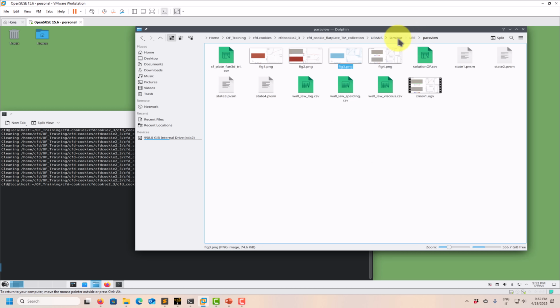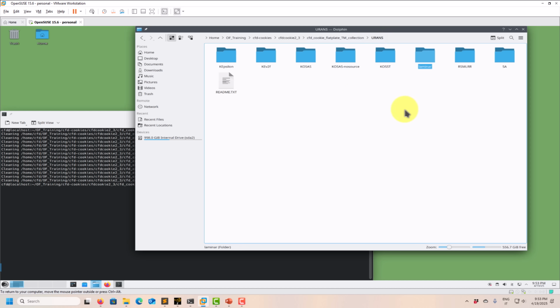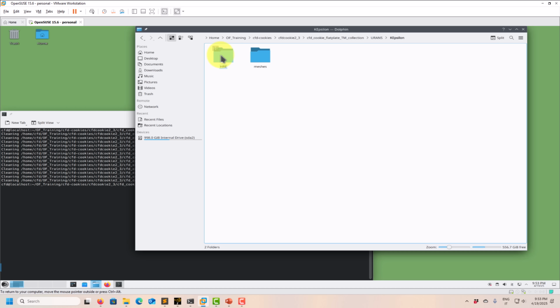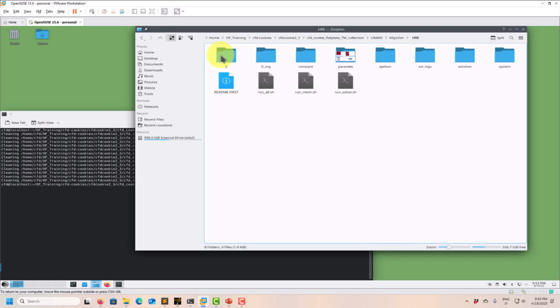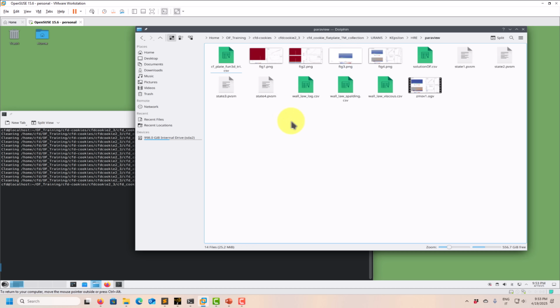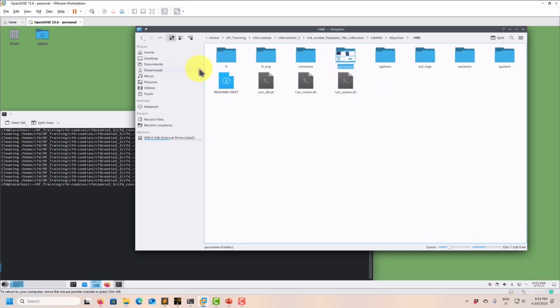Statistics are very important. So we looked at the laminar case, and now let's move to the other extreme and talk about K-Epsilon in this model. Remember, K-Epsilon uses wall modeling. You have some options with the low Reynolds version, and it's up to you to rerun, but in this case I chose standard K-Epsilon wall modeling, okay? And let's take a look. Remember, the setup is exactly the same, the only difference being the time step and the discretization in time.